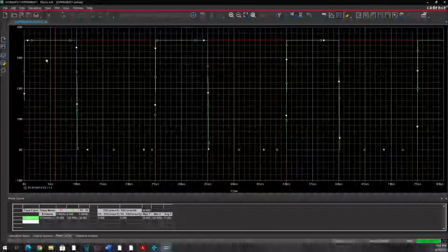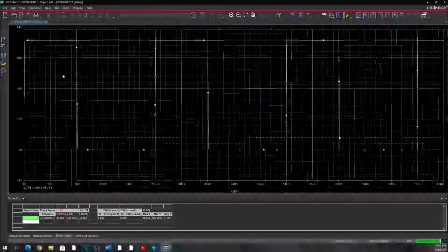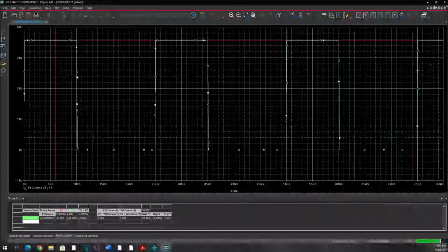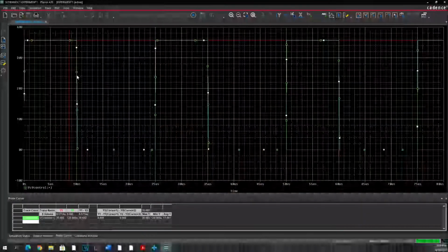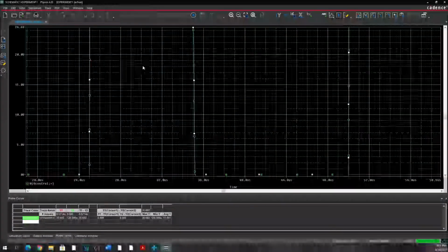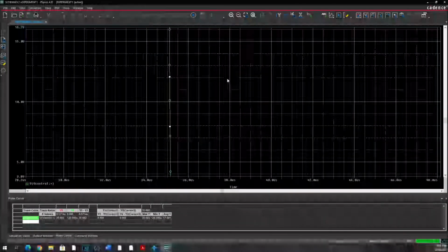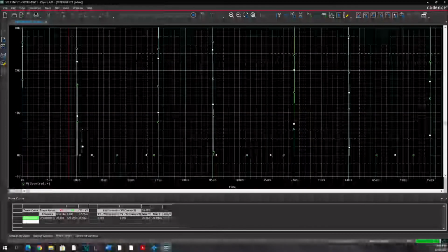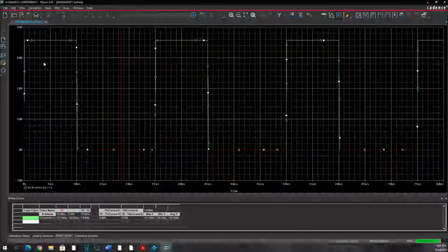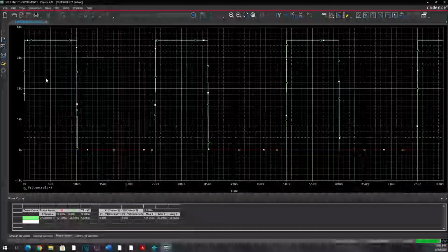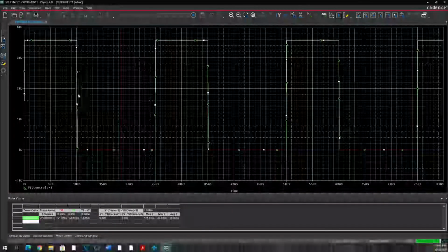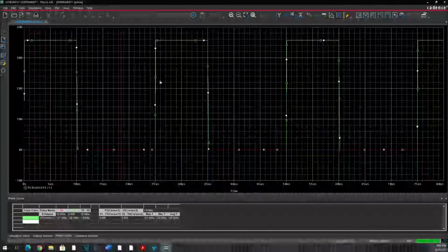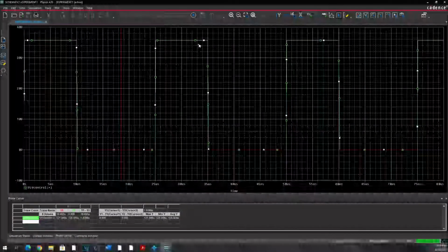We can also see the rise time and fall time. Here, look. In the previous simulation, we can hardly see the rise time and fall time of the pulse waveform. But here, we can somehow see that our pulses follow the parameters of our control voltage, wherein it has a fall time of 1 nanosecond and a rise time of 1 nanosecond here. You can see the slight slant of our pulse waveform. And it also follows the control voltage parameters, wherein the pulses last for 10 microseconds, then fall for 1 nanosecond, then 0 voltage, and rise again for 1 nanosecond, and peak again for 10 microseconds.